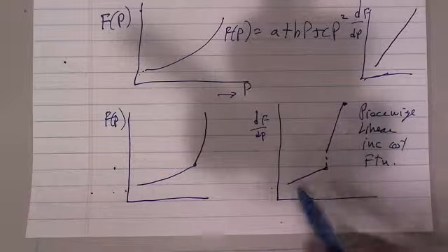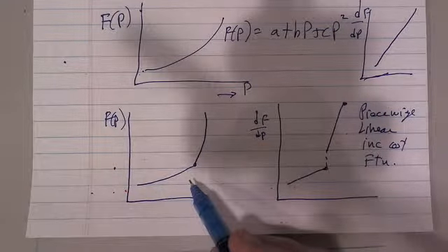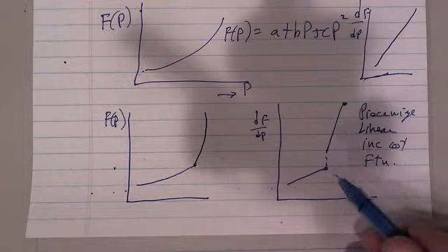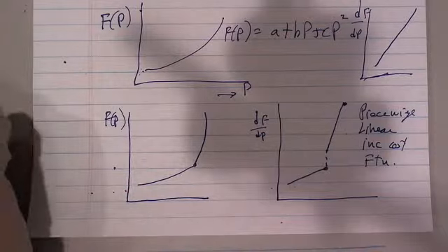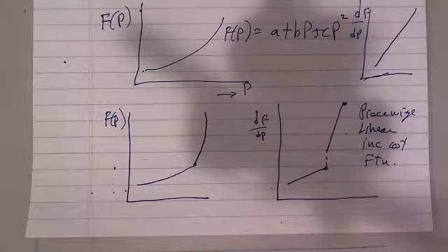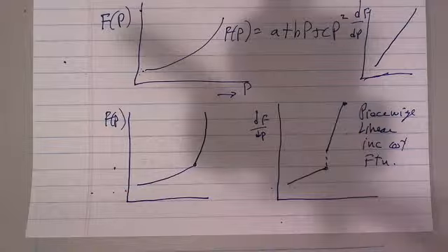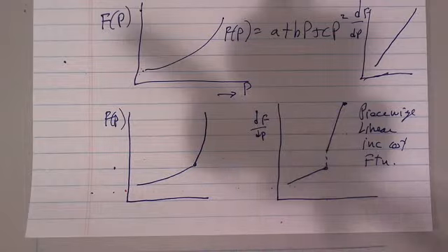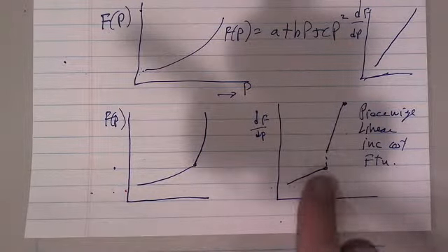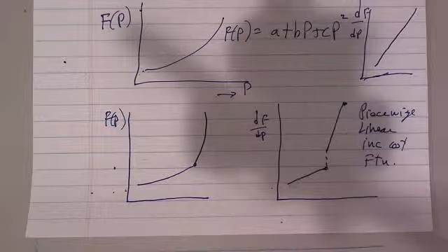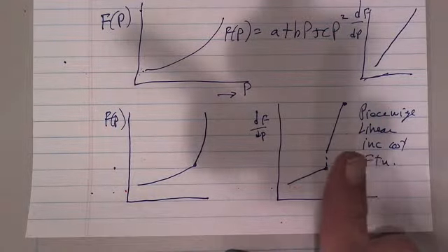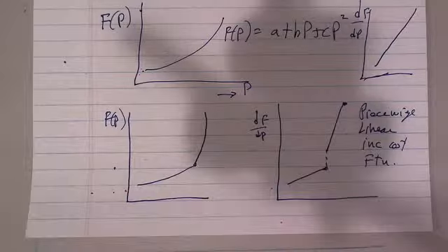And yes, this data should all be related to the tests that the mechanical people did, but the people that operate the system know that they don't want certain slopes to cause one generator to race ahead while the other generators sit, and so they adjust these to get certain operating characteristics. So we'll come back and talk about piecewise linear curves, but they are very practical.